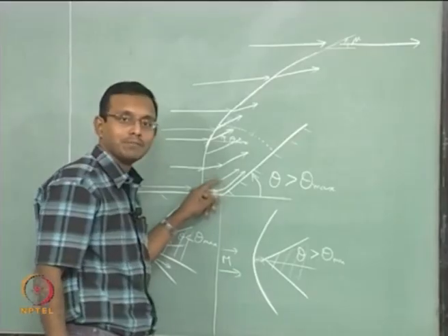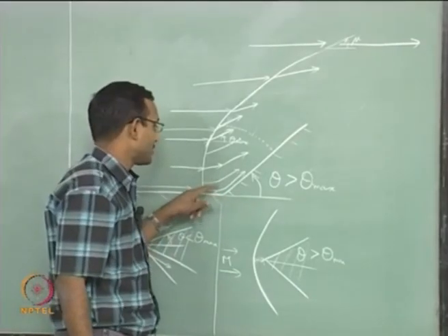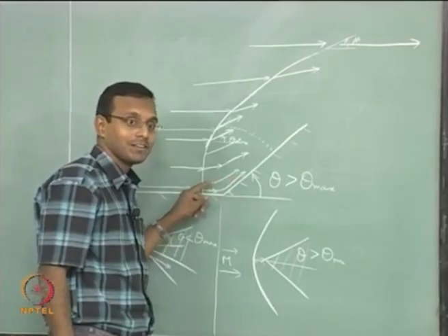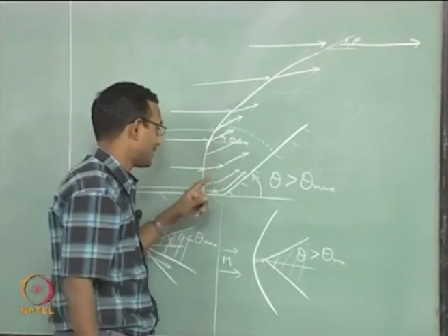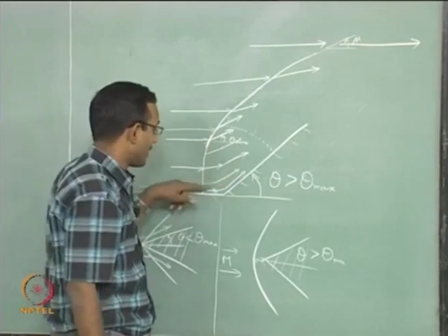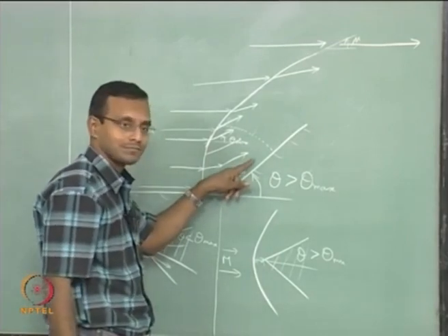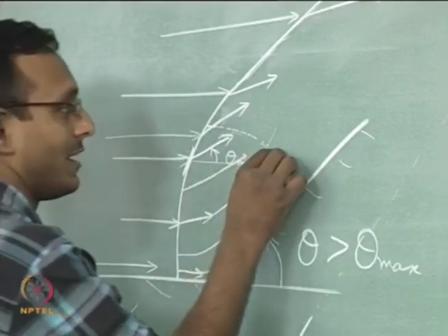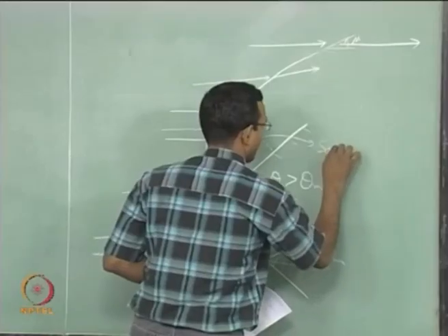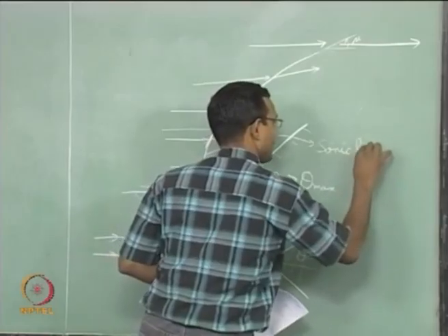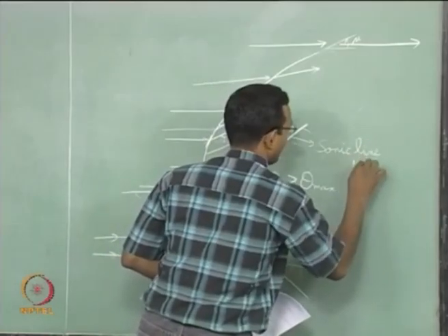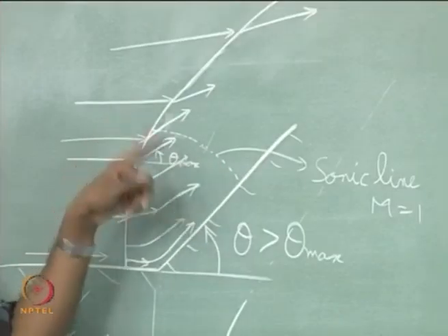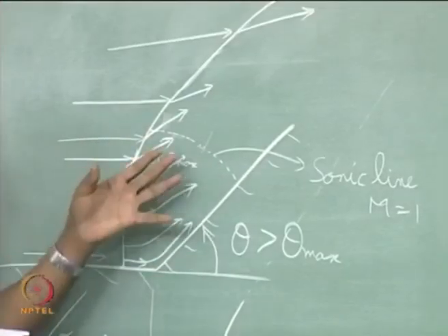It will have a region of contracting stream tubes. What does that mean? Subsonic and stream tube contracting, area decreasing, the subsonic Mach number will increase. That is also happening in here, so we are accelerating the flow here. That is why this dotted line, which corresponds to the sonic line, is nothing but m equal to 1 along that line. I will go to a point where m equal to 1 sits here.